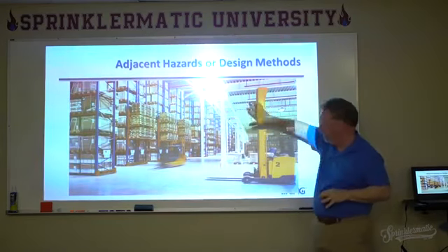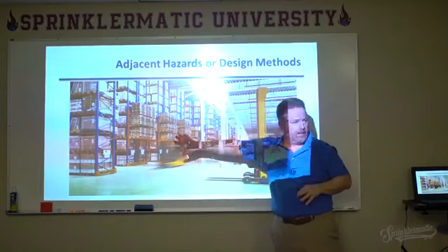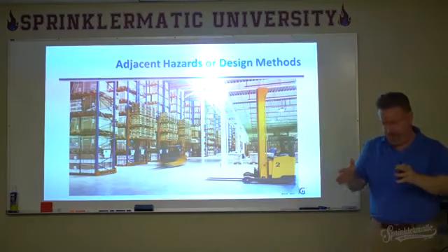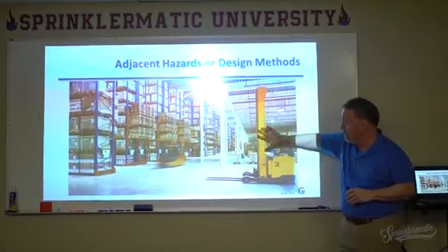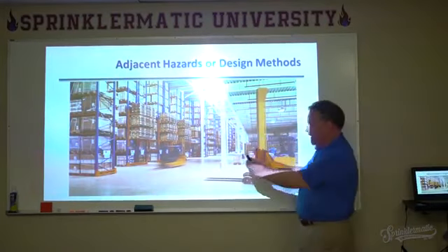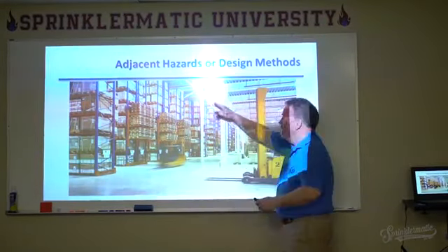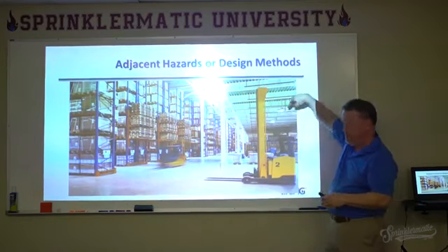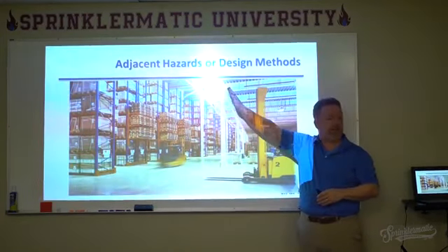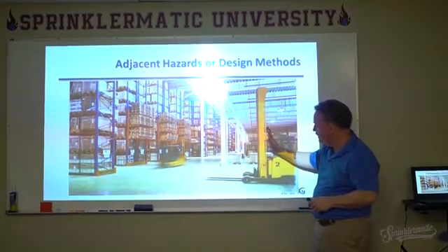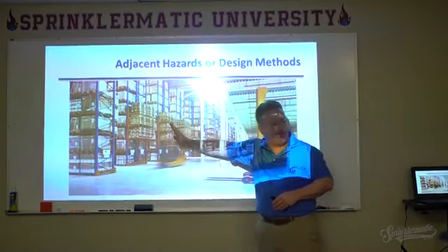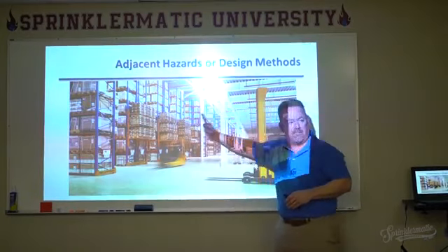You don't need quite as much water there as you do over here, but the standard allows you to and requires you to actually design this separately, but separate this space here by either changing the roof height or by having draft curtains up above, so that we don't have a fire in this case here operating sprinklers out in this design area, or vice versa.